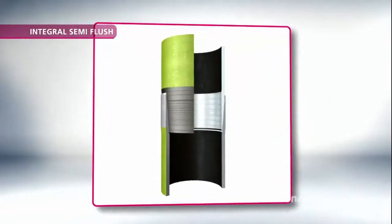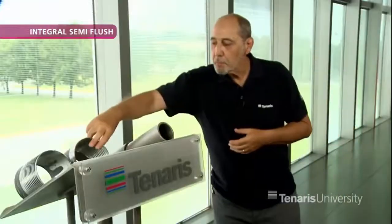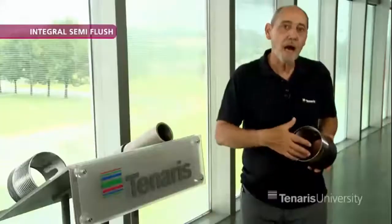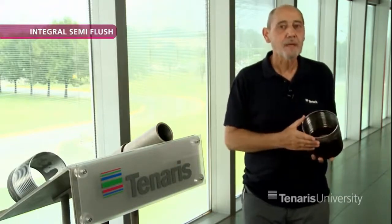Then we have integral semi-flush or near-flush connections, which have an OD slightly larger than the OD of the pipe body, generally from 2 to 5%. Near-flush connections require an expansion at the box and a swedging process at the pin end. During the expansion of the box, the external diameter is enlarged through a cone at room temperature, resulting in a diameter a little bit larger than the pipe body.